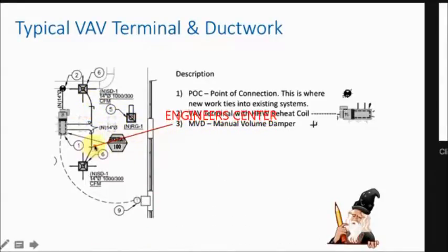And volume dampers are represented by a little slash with a handle to adjust the volume. So every piece of air distribution, unless it's the only one off the box, should have a volume damper. That way when they do an air balance, they have something to adjust with.